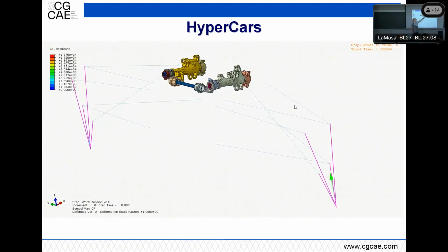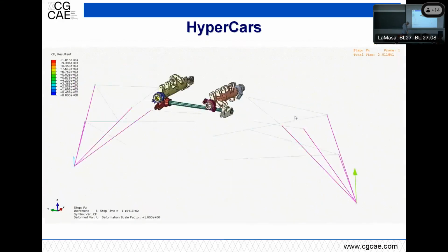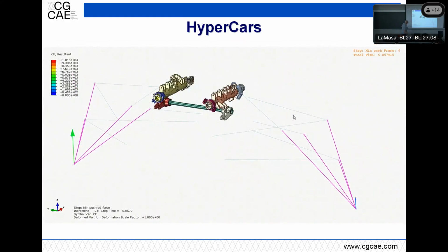So this one is again called a rocker. It's a similar concept to what we saw before, but clearly we have a lot of other things attached. We have a transversal damper, a transversal spring, a moving mass, the so-called inerter. And the model here is still non-dynamic, it is static. It's done to check what is the position with the maximum stress among all the load cases.